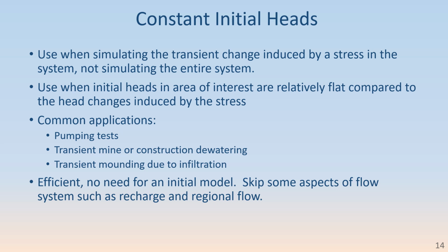You're just simulating the transient change that the pumping induces. This is fine for that application, and where it breaks down is if you want to simulate the long-term evolution into a steady state. In that case, you'd need to run a transient model from an initial condition from a file.